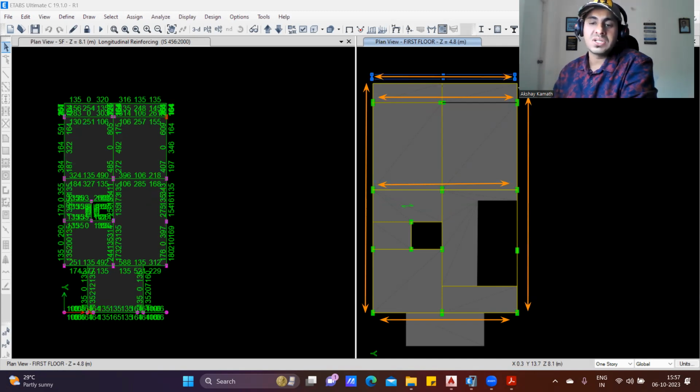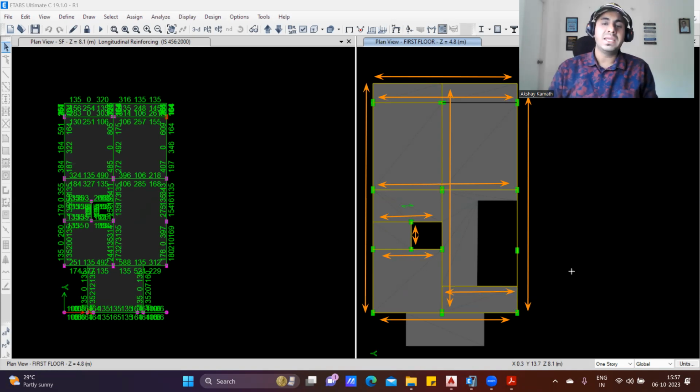And then this is continuous, B8. After that, whichever is left out, a single beam, for example, say this is not continuous, then you give a single name like B10. This is B11. This is B12. Done, no? And this is B13. Got it? Understood the concept? So in this way, we'll do the designing, and then we'll give the names and the reinforcement details. Understood the concept? So this is how we are supposed to do it.